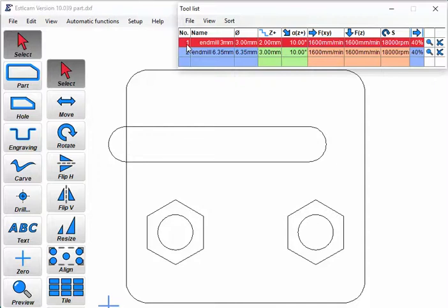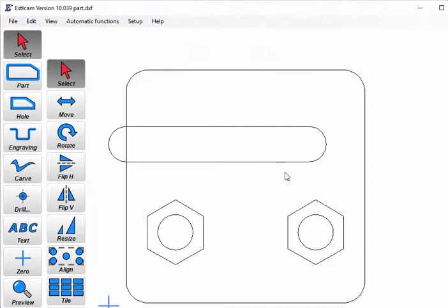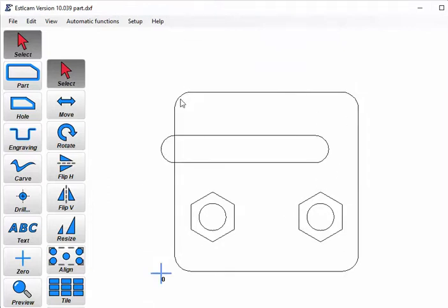So what I'm going to do is just use one end mill, 3 millimeter. I'm going to get rid of this because it's all going to be in that. I'm going to be doing the slot first, or I could do the holes first and put screws in it to hold it so we could do the outside, or I can do holding tabs, and there will be a piece of wood underneath this so we can cut into the wood.